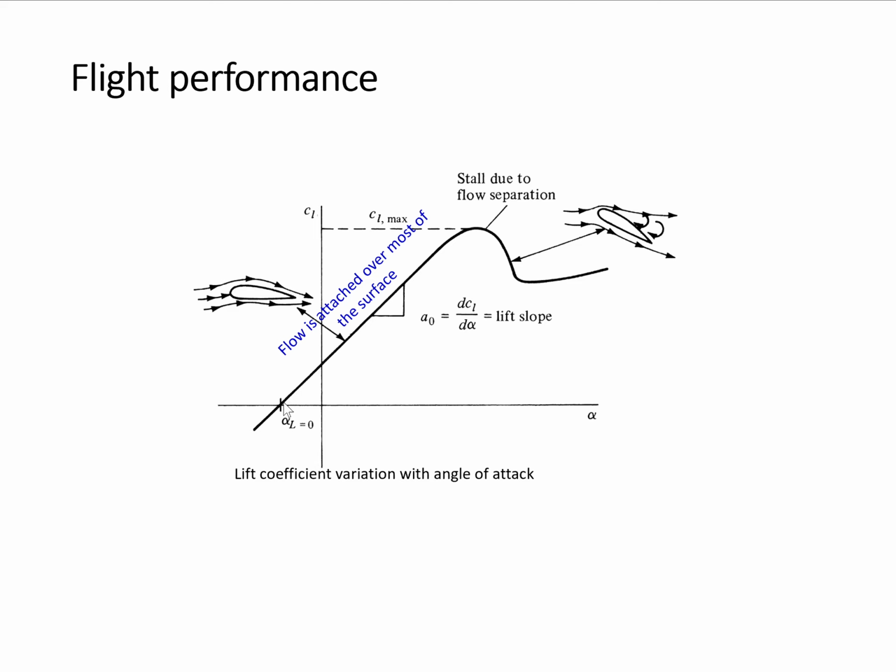So we go from zero lift coefficient, which essentially means zero lift, to a maximum lift coefficient, which is called the stall condition. The stall is, if you want to think of this in terms of solids, analogous to the yield point, where the material yields to plastic deformation. This is where the flow is completely separated and the vortex shedding happens. Then you will see a dip in lift coefficient.